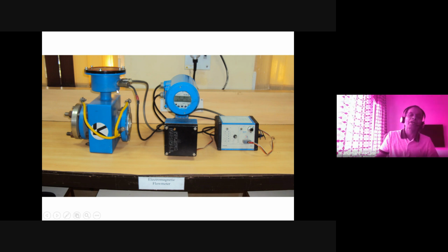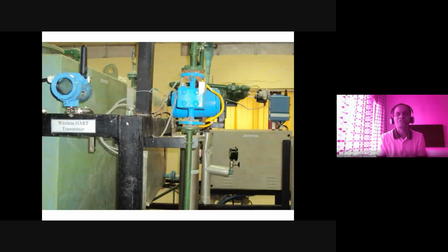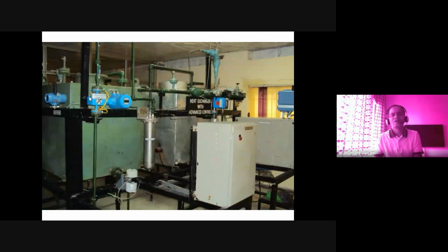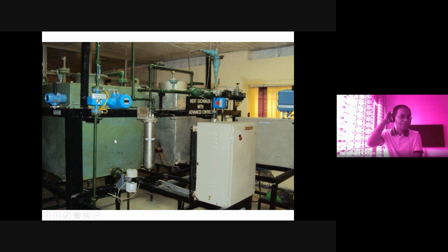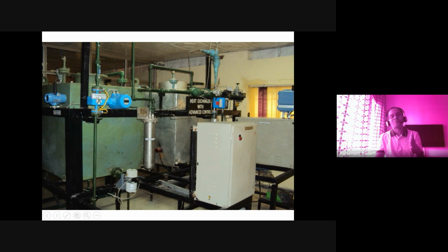Normally, it is tested or calibrated in the flow lab where a pipeline is created. Two tanks are there, and in this picture you have seen this type of setup. Like this setup, we fit it there, and we measure through a metered tank. Metered means flow in liters per hour or meter cube per hour, how much the tank flow has come. So we calculate it, and whether the same is noted by these sensors, that way the sensors are calibrated.